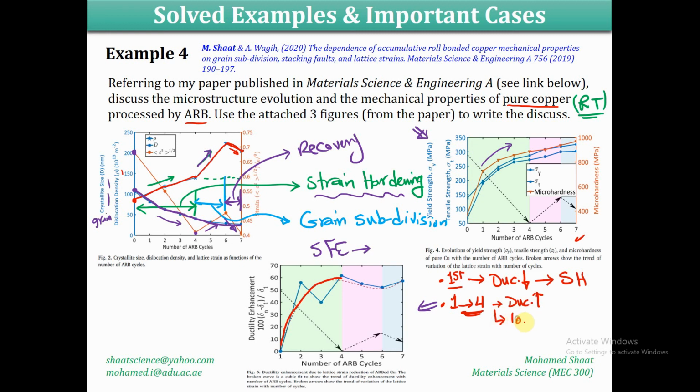The first reason is the low stacking fault energy of copper. Something that is well known for any material is that the ductility is related to the stacking fault energy of the material. That is one of the lattice properties of any material. I won't explain it in more detail. But in case you have a material with a low stacking fault energy, it is more likely to be ductile. So copper by default is a ductile material, and this is what we knew about copper.